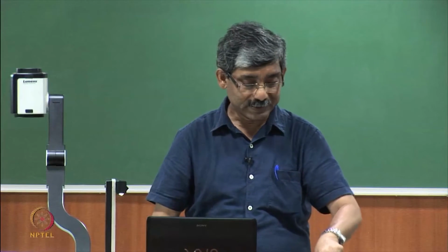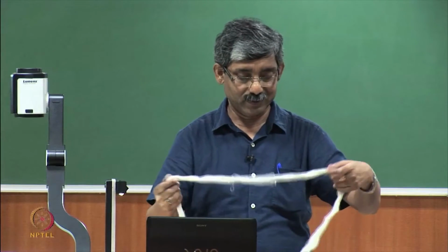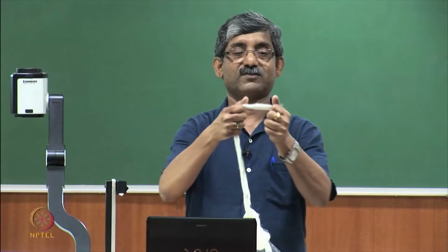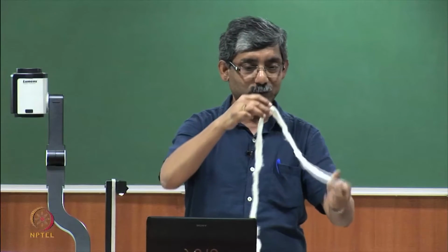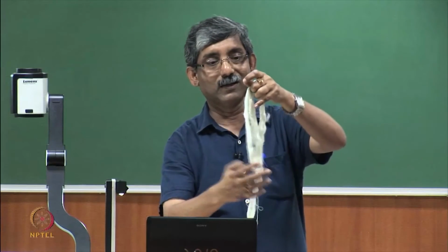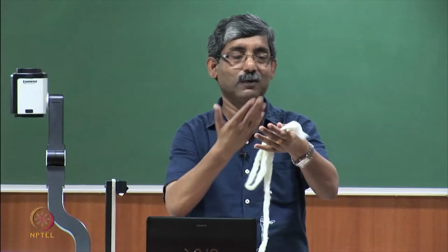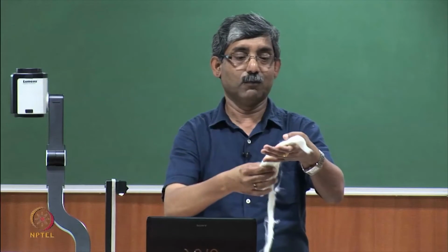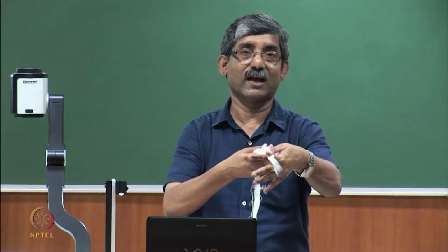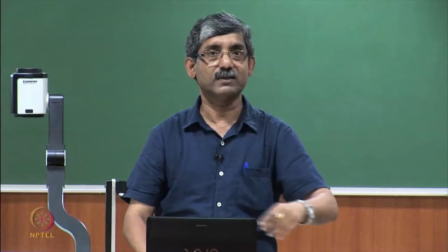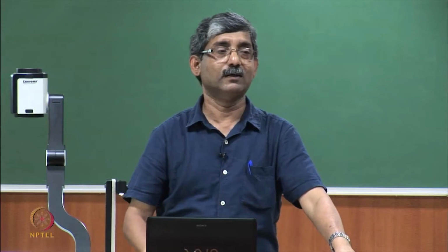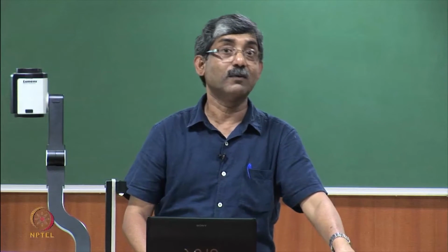Typically, if we stretch any material, any strand, we add irregularity, but if we double, if we use more than one strand, then we are reducing the irregularity, and we will see there are some equations to calculate the addition and reduction of irregularity.